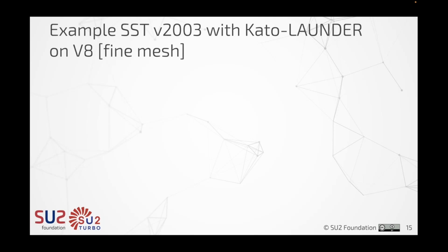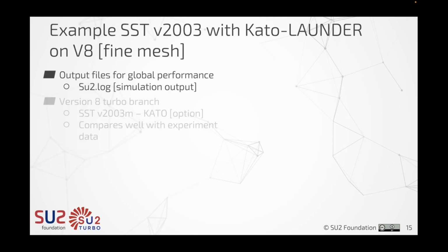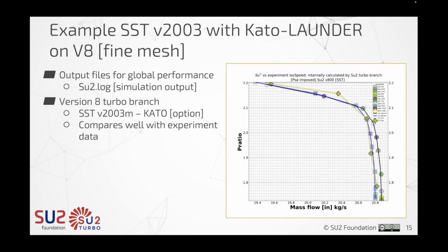So in my study for the fine mesh, just to show how SU2 behaves, I used the Kato-Launder option for SST 2003 on the fine mesh, and it compared well with the experimental data.